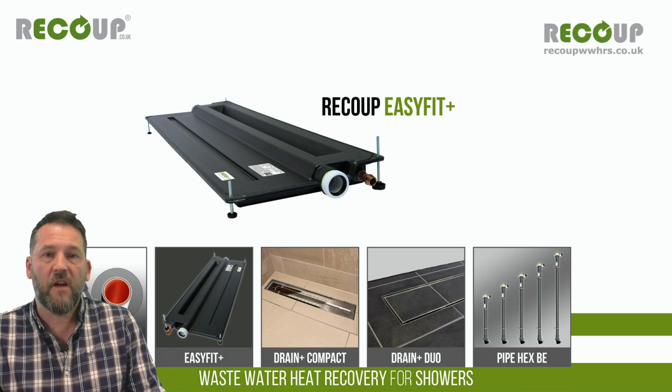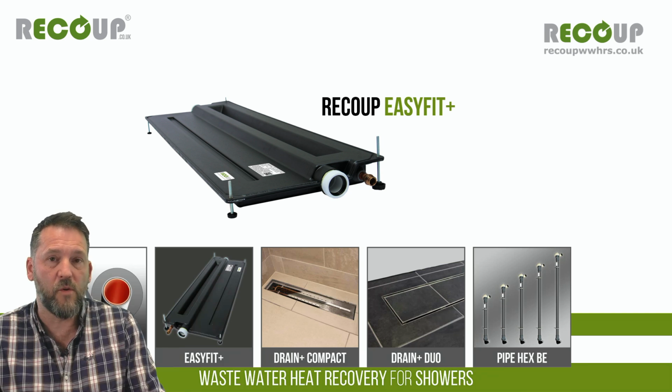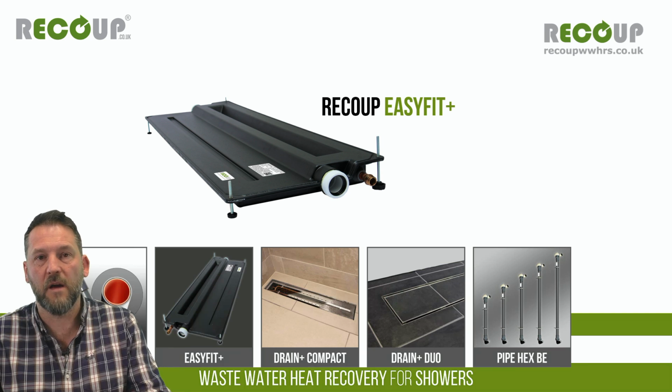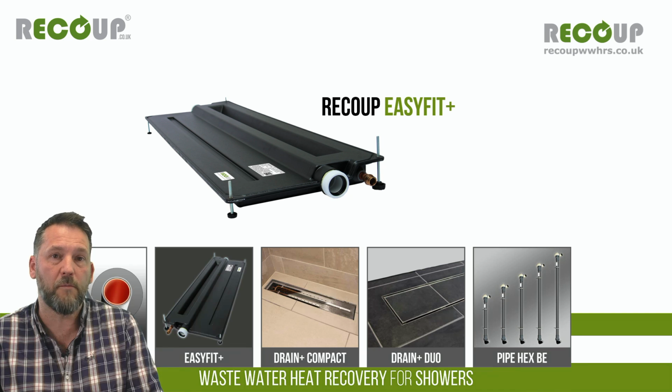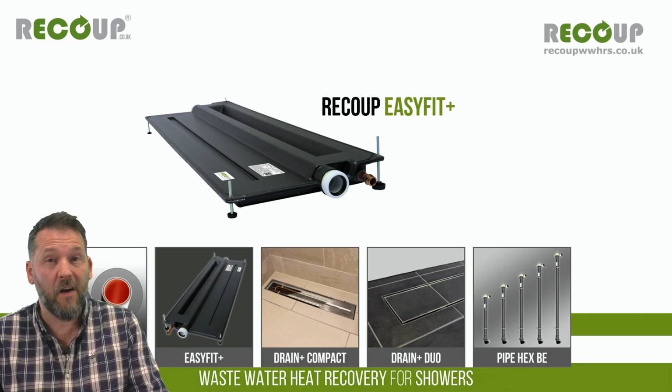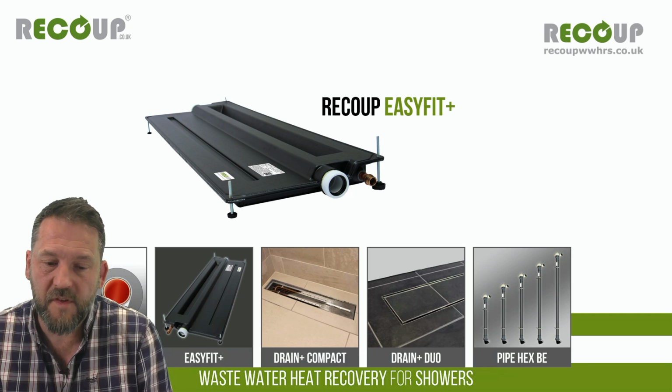Wastewater heat recovery as a technology is heat source agnostic, so gas, electric, renewables, it really doesn't matter to us as long as the hot water generator can accept a preheated incoming cold water main, and in reality most things can. Combi boilers, for example, can, cylinders can, most renewables can. So it normally doesn't matter from our point of view what fuel source or plant type is creating the hot water, as long as it can accept an incoming preheat. If it can't, then you've always got system B as an option anyway, where you're just connecting to the cold side of the shower mixer. So that hopefully covers that.